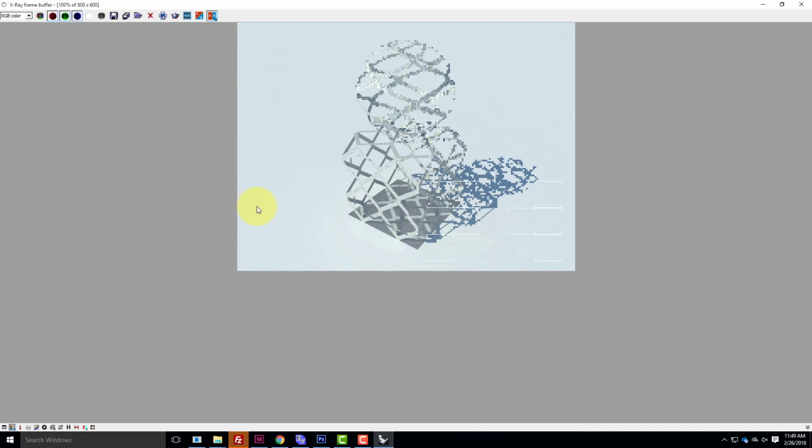My particular scene is a little bright for the projector, so it's hard for you guys to see. But notice the shadow is also being cast as if it were transparent, so we're getting the shadows accurate to this as well. There's probably a little bit more texture mapping that needs to be applied. This chain link is a little bit large for the size of this object, so I would go in and adjust the texture mapping to compensate for that.